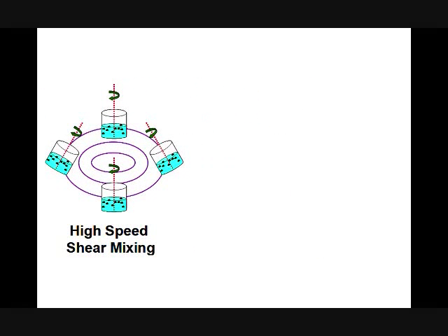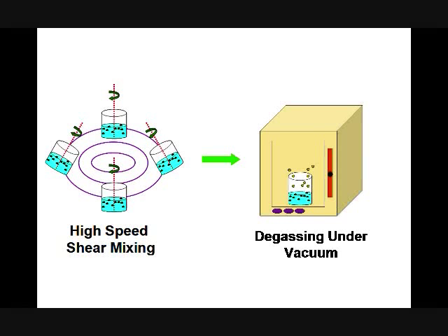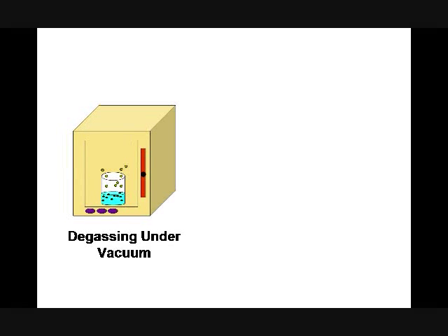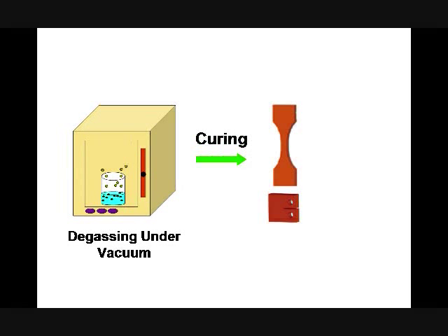To remove air bubbles from the sample, it is degassed under vacuum for 10 to 20 minutes, after which the sample can be poured into the molds, and after 24 hours, the samples will be cured and the nanocomposite will be ready. Graphene epoxy nanocomposite is an ongoing research topic, and experts are currently working to improve its properties. These types of nanocomposites have great potential for various industrial purposes, and there may be more news about them and about their new applications.